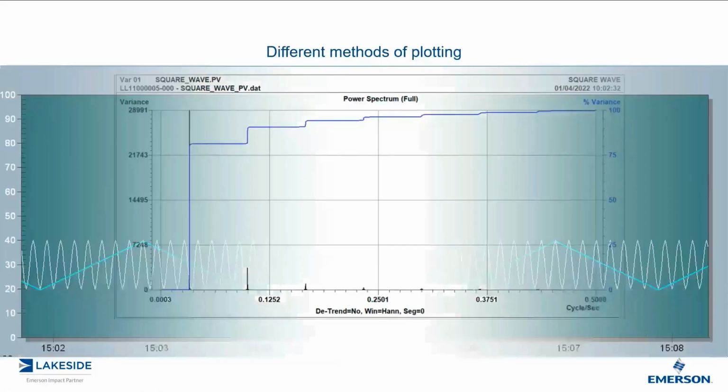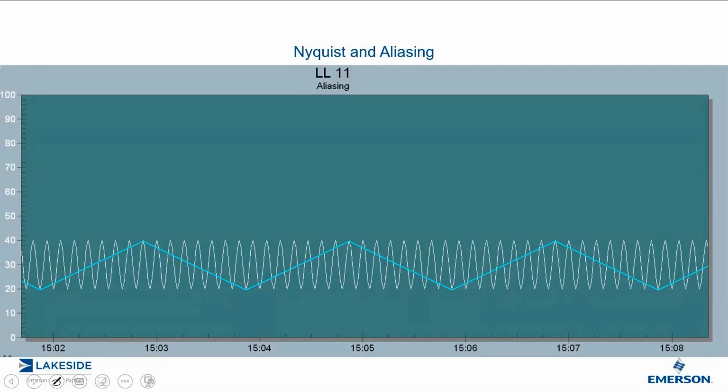And how do we prevent this? Before we sample, we need to put the signal through an anti-aliasing filter. So if I've got my signal coming in, I have to put it through an anti-aliasing filter, and of course I have the world's worst handwriting, prior to sampling the signal here.